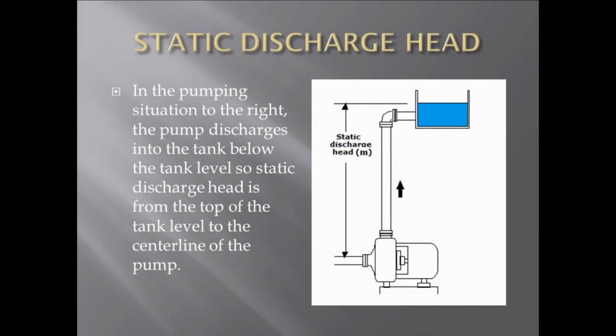In the pumping situation to the right, the pump discharges into the tank below the tank level. So static discharge head is from the top of the tank level to the center line of the pump.